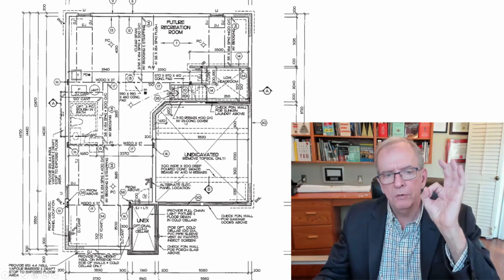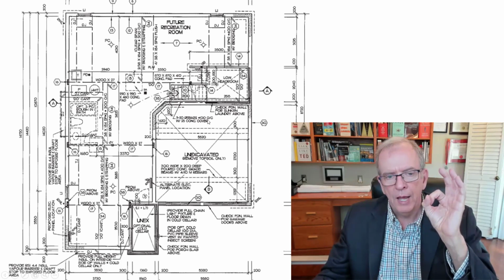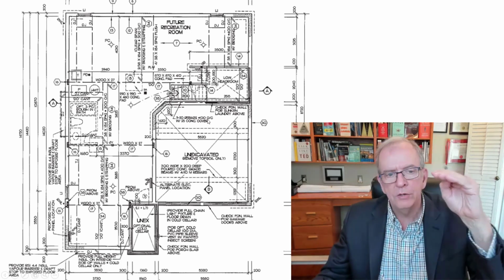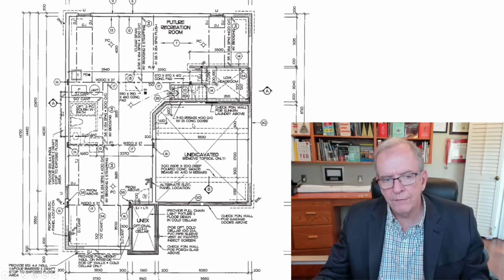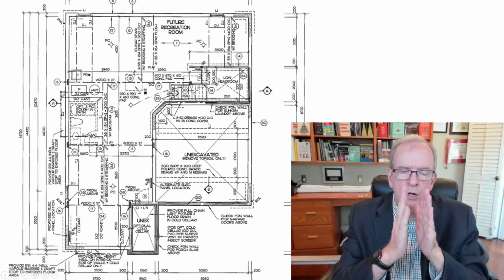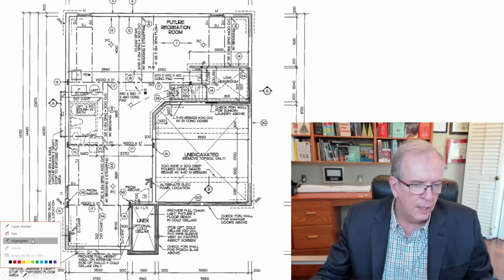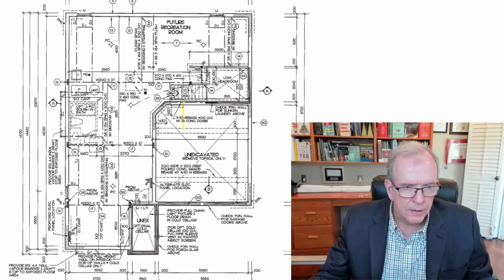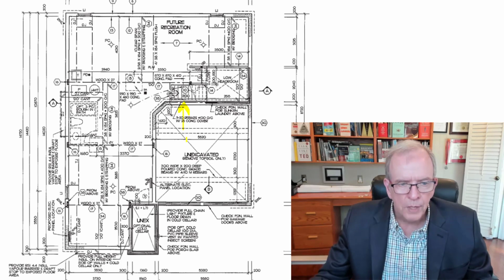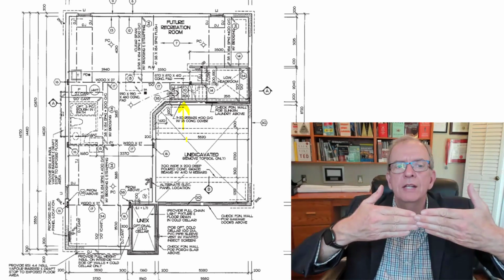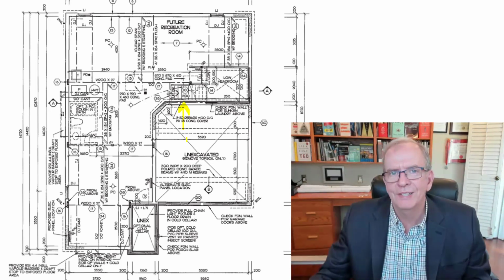So 20 millimeter rebar, that's the diameter, at 100 on center, and they're near the top with 25 concrete cover. That's how much concrete has to cover the rebar, and the rebar is placed where the force is coming in. So the force is coming this way against the wall, and so that's going to put those rebar under tension, because that's where steel has its strength.